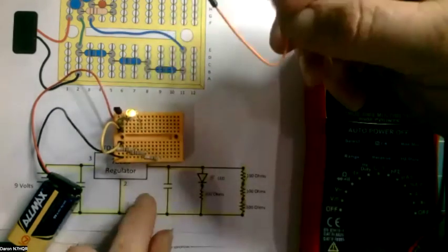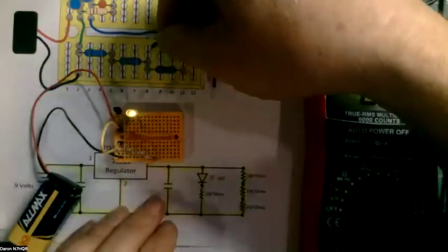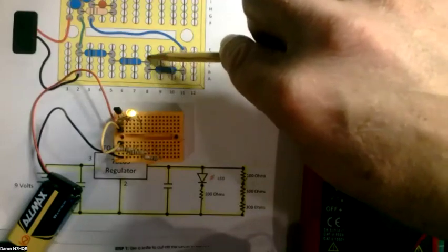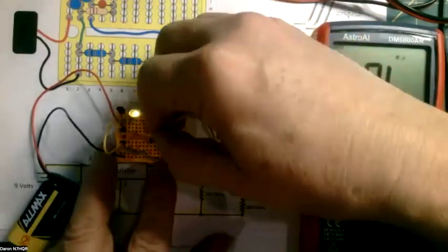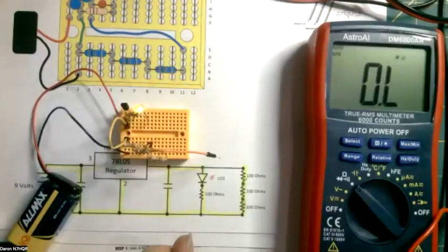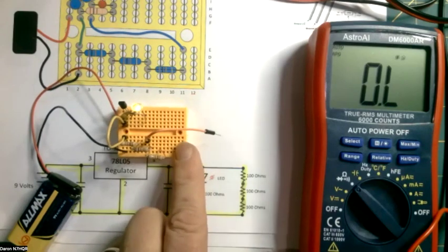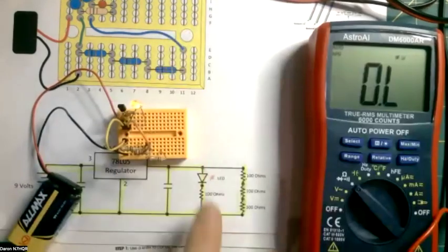So we're going to do that with another jumper. Darren, I'm going to have you go to the second resistor instead of the third. Okay. So that would be right here. Joe wants us to connect to this, which is column 8 here. And we'll put a jumper in that column. And then to complete the circuit, we have to take the other end of that jumper and go to our 5 volts, right? Which is the output of this regulator, which will be on column 3 on the top, like that.